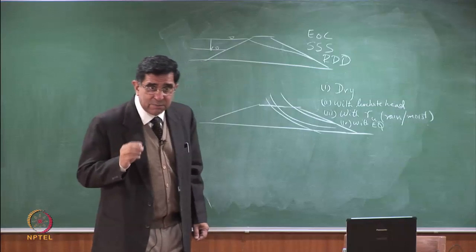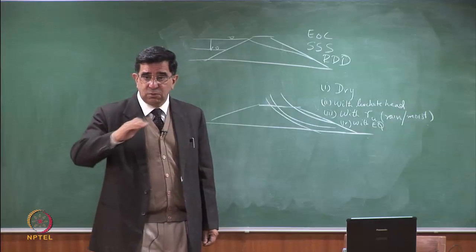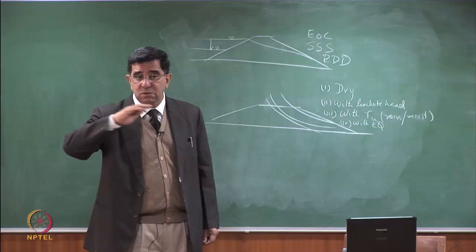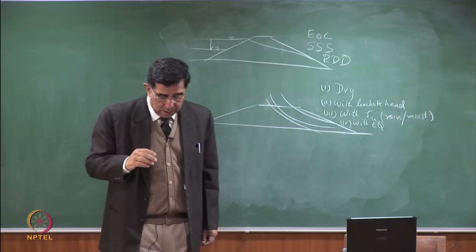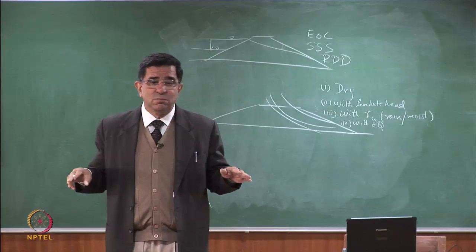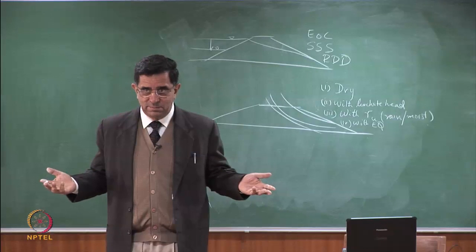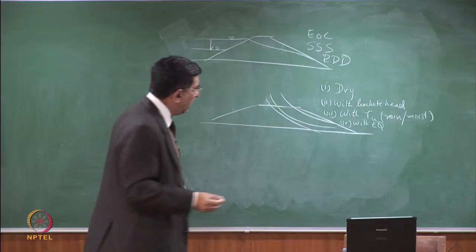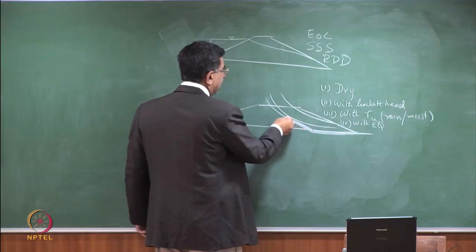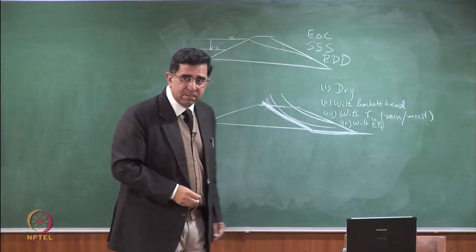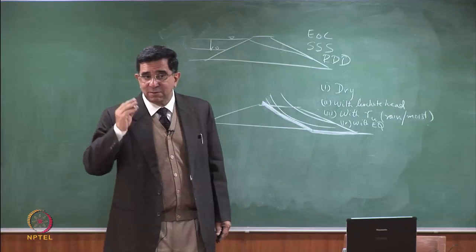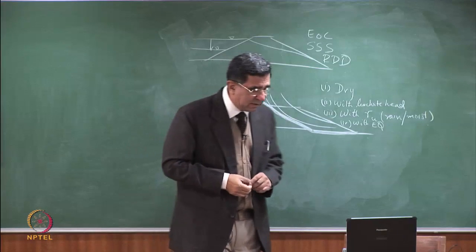And one more failure that I am talking about is, I told you, because we have a base liner which may have a geomembrane, that may be an interface which is very weak. In all the landfills that we have designed, we have kept the base liner smooth because we said there is no slope, right? But we did not realize that you can have failure like this. So our delta is very low for the base liner. Delta is high for the side slope liner. And see what happened in this case study.